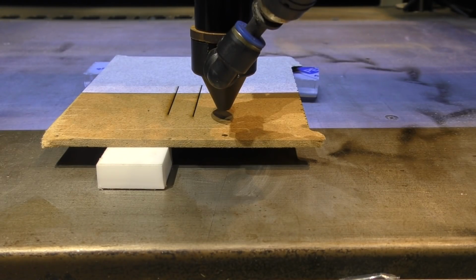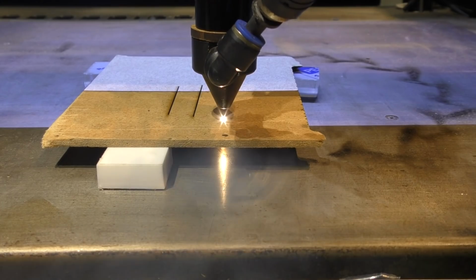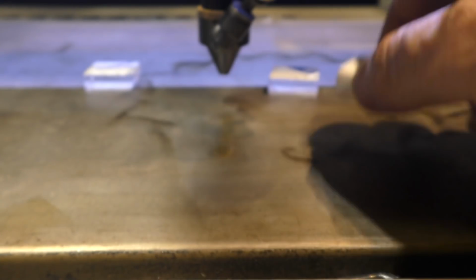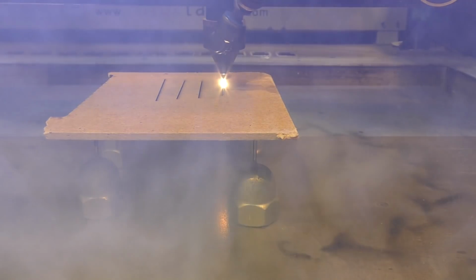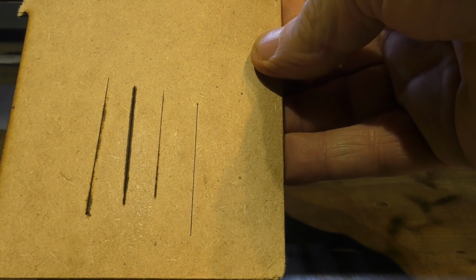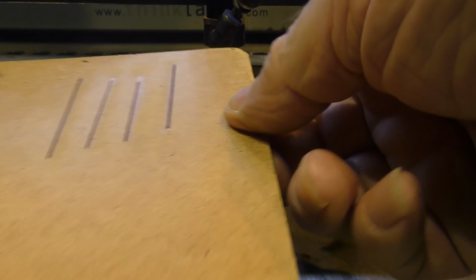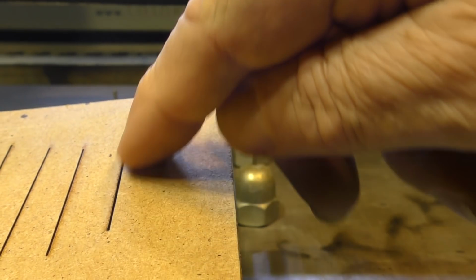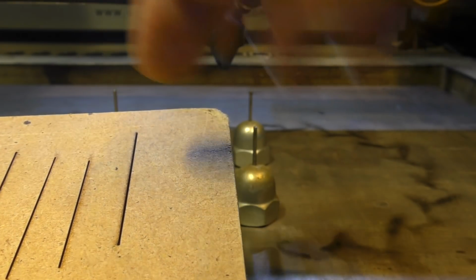Now put it on 10mm spacers to keep it away from the surface, because although I got a reasonable cut through, I got terrible back reflection off of this base plate. So we're still getting some reflection off the back plate, so I've got to go even further away. On the back, I've got rid of all the reflection. On the front, I've got rid of all but just the merest hint of that marking that I was talking about, because most of the air is going through.